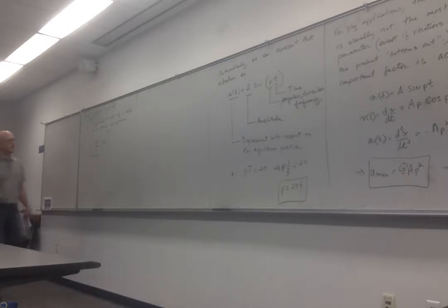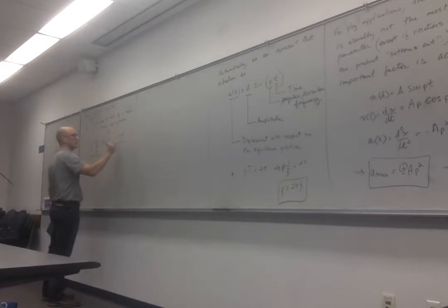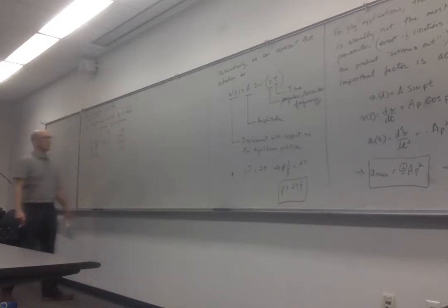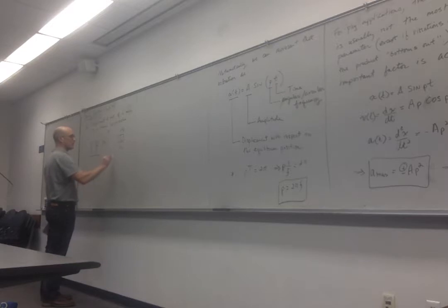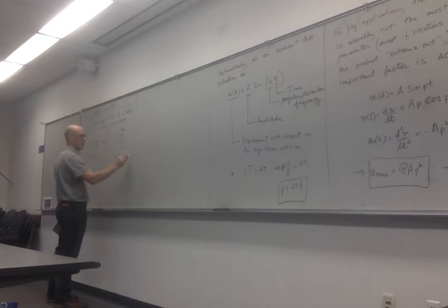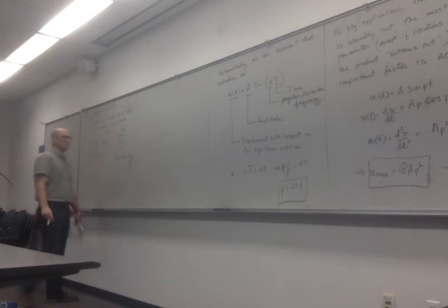So if you look at this with a mass on the spring, you do the free body diagram on this. What you're going to have is its weight, and the force of the spring. It's pretty simple. If it's at rest, that means there's no acceleration, so the sum of the forces is equal to 0. So in here, we can find that the force of the spring, minus k delta st, is going to be equal to the weight, mg. So this is obviously the weight of our object.